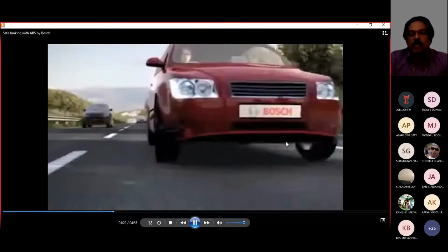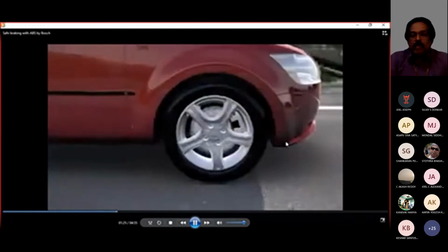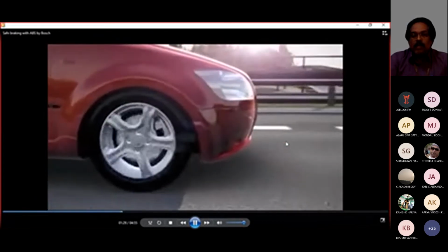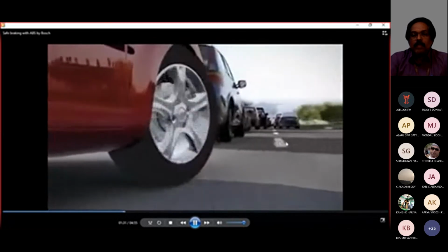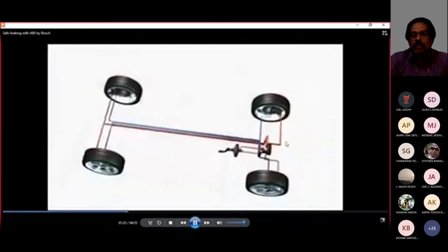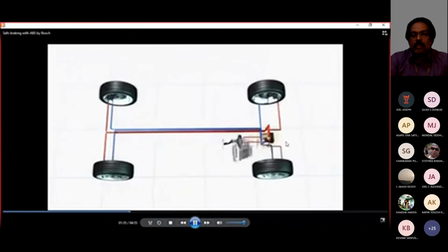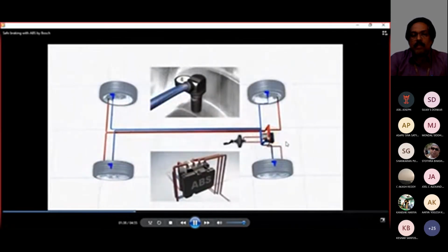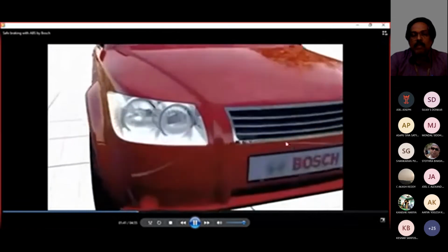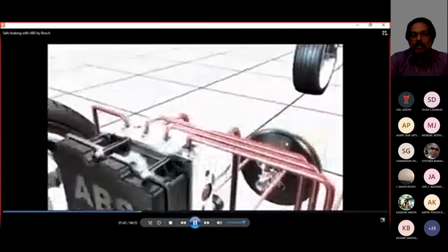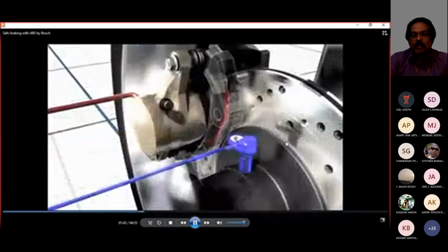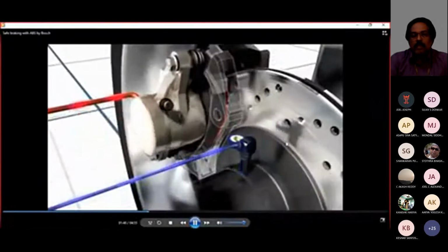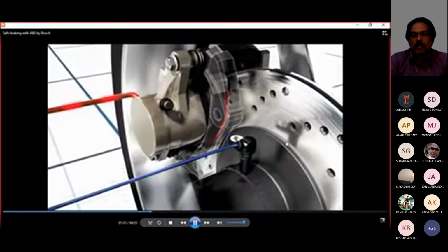ABS, the anti-lock braking system from Bosch, prevents locking of the wheels. ABS ensures that the vehicle remains steerable and stable while fully applying the brakes. The ABS control unit also continuously monitors all wheels by means of wheel speed sensors. Should the system recognize that a wheel is locked, ABS immediately intervenes and systematically regulates braking pressure. ABS can regulate each individual wheel within milliseconds.